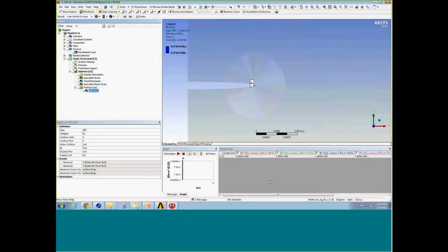For most simple problems like this, if you look at the results for the different contours, there's usually error in the first one, but as you start moving outward, you should see that eventually they kind of converge to a solution. So by the sixth one, for this particular case, we have a value of 0.0746, which also shows up in the details. And now you can compare this value to the material fracture toughness to determine if this crack would propagate. And that's kind of the general procedure.